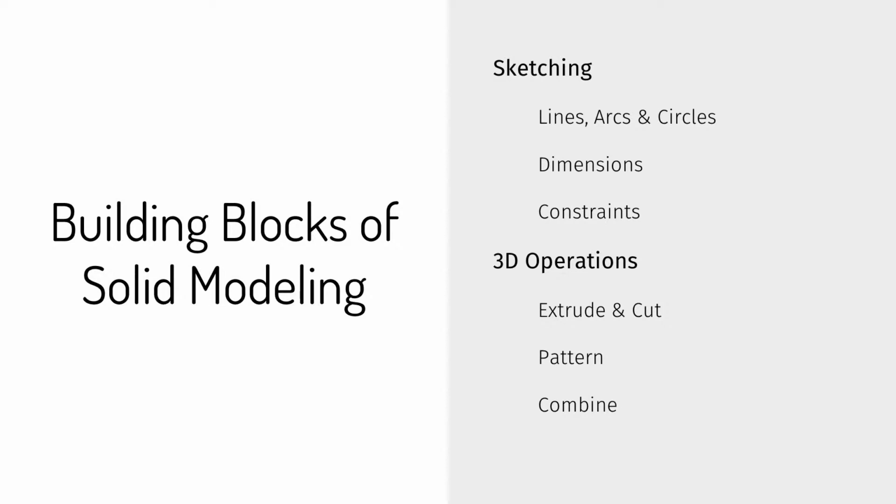So moving into 3D operations, after you have your sketch together, you'll probably be familiar, but like extruding in 3D. So that's creating shapes from the profiles that you've made in your sketches. You can extrude and cut with profiles, and you can do that on an object. So you can extrude an object, and then say you wanted to make a tenon that's perpendicular to that object. You can then cut that tenon's profile hole. So that's how that works. We'll take a look at all this.